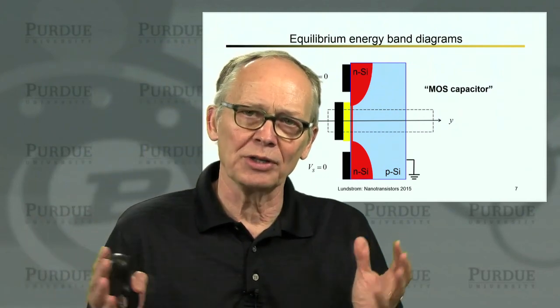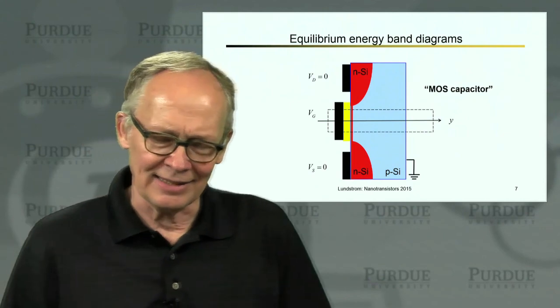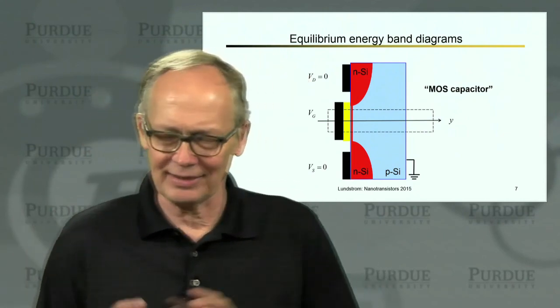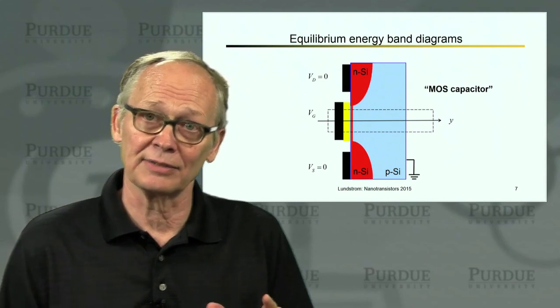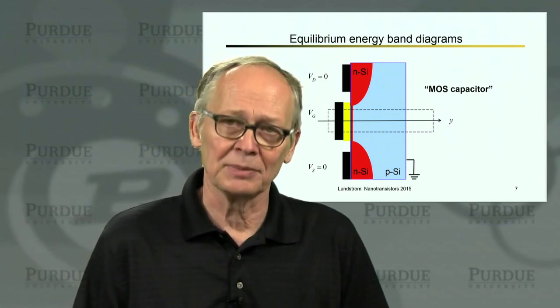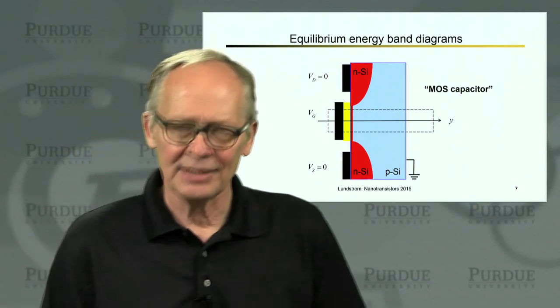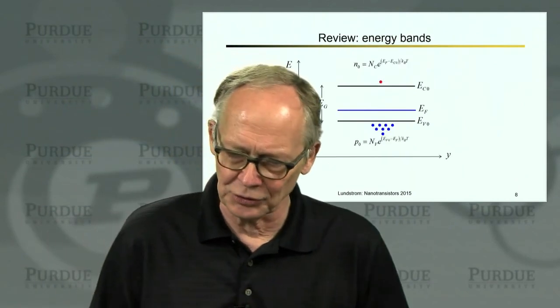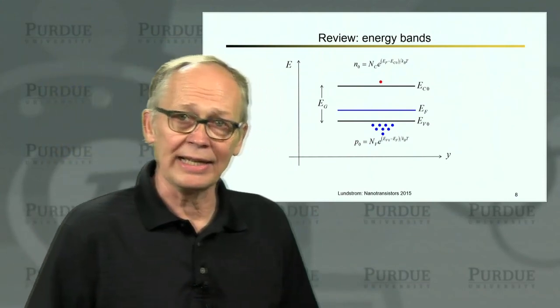We're going to ignore the presence of the source and the drain and just assume they're so far away that they don't really affect things. They do in practical devices because these channel lengths are very short, and that brings up some very important factors called two-dimensional electrostatics that we'll talk about towards the end of this unit.